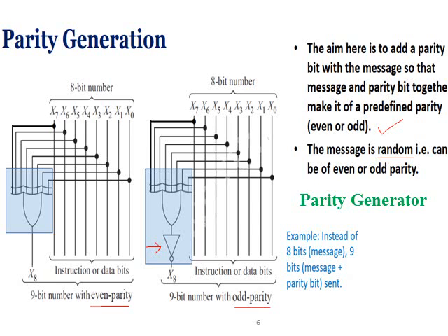So what happens? The output of the XOR gate will be 1 for an odd number of ones, then that will be converted again to 0. So net the number of ones will be odd. So this is a circuit of odd parity in the middle. Okay. The data or information we have no control over, it will be random. So based on the random data coming as input, this XOR gate generates even or odd parity, it will send to the receiver. Now let's see the receiver circuit.